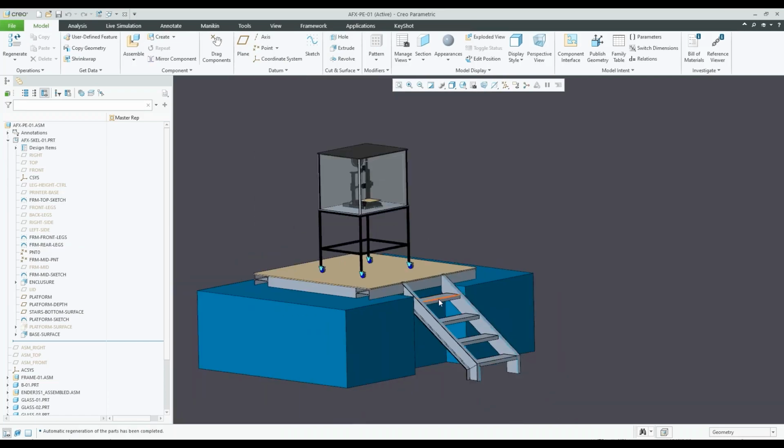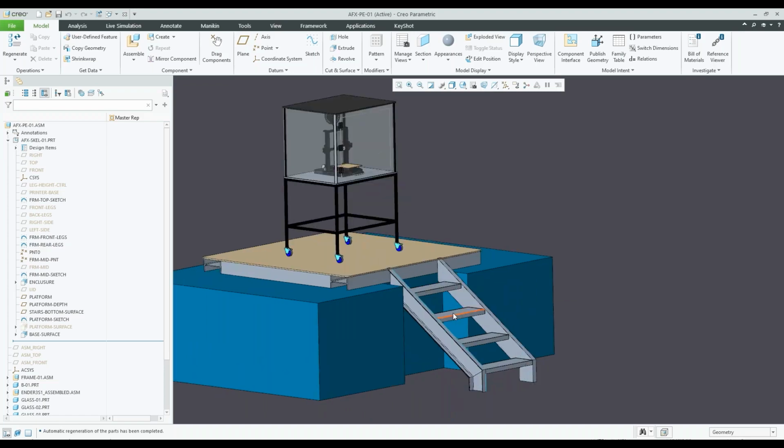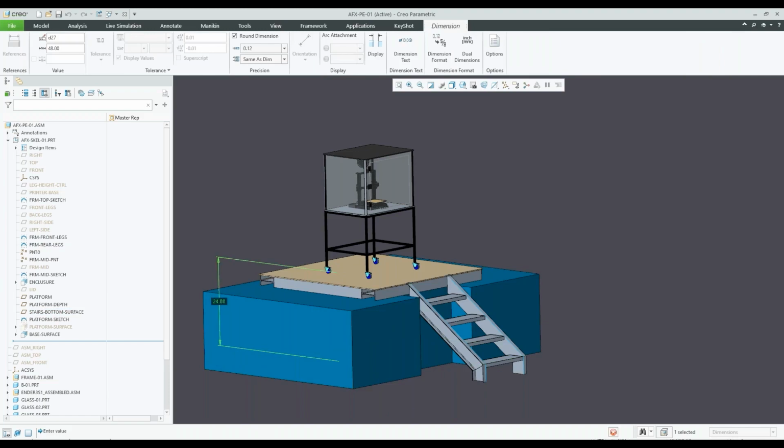So by just changing the stair base plane and extending that further down and increasing that height, the advanced framework extension knew that in order to maintain those stairs, it had to add additional steps. I can always change that back and grab this guy and then change this back to 24, for example.